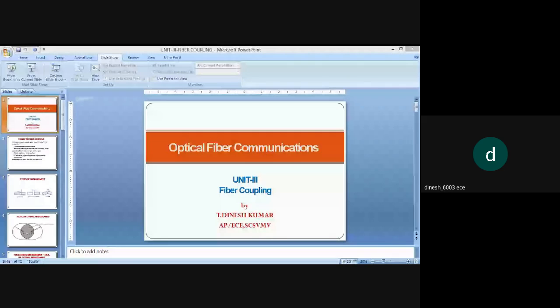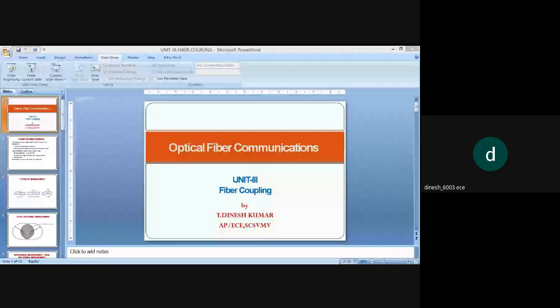Power is lost here, and here power will be transmitted. This is calculated by the critical acceptance angle theta c, which plays a major role. The optical power emitted in the ring of width x will not be intercepted by the receiving fiber. So the loss is calculated by minus 10 log of a divided by a plus s tan theta c, the whole square.